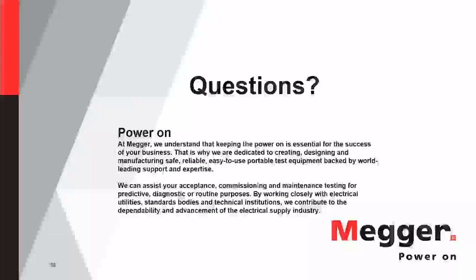Okay, this question was from Felix. He asked, how do you figure out contact bounce from the travel diagram? I get this question a lot because people think bounce is from the motion. What bounce actually is, you get from the timing. You can not hook up a transducer at all and still get a bounce. The IEEE and IEC definition of timing is from closed coil energization until the first metal-on-metal contact. So the first time those contacts touch is when you measure your closing time.